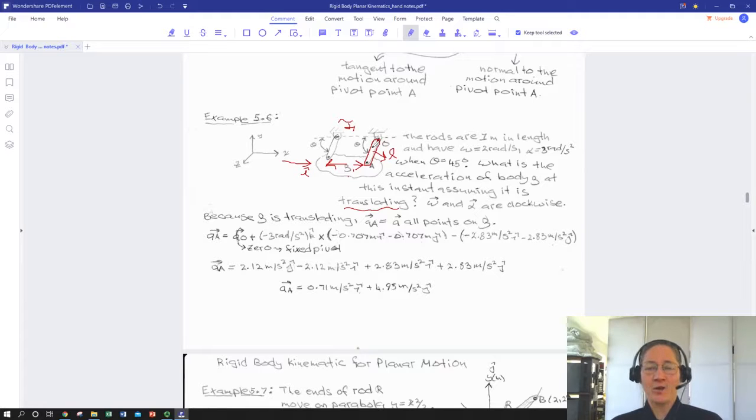And we're going to look at the motion of L with reference to our fixed reference frame, which is like the ceiling that these bars are bolted to, up where the hinges are. Okay, so our point that we know the acceleration of with respect to our fixed ceiling reference frame is O. It's the hinge. And the nice thing is its acceleration versus the ceiling is 0 because it's bolted to the ceiling. It's the hinge. We drilled some holes and bolted it down. It has no acceleration versus the ceiling.